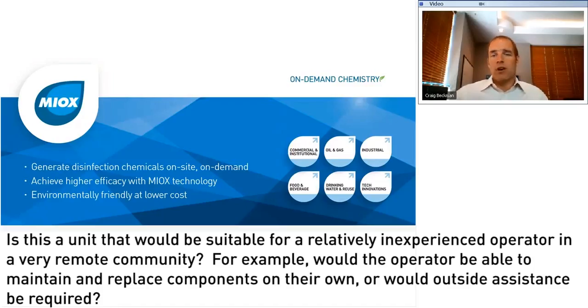The systems are fully automated all the way down to the unit, so that if an operator mistakenly shuts the inlet valve, shuts the outlet valve, runs boiler condensate water into the unit and it's way over temperature, the system will shut itself down and give the operator feedback on what alarm shut the unit down, and they can then go check for low inlet water pressure, high temperature, etc.